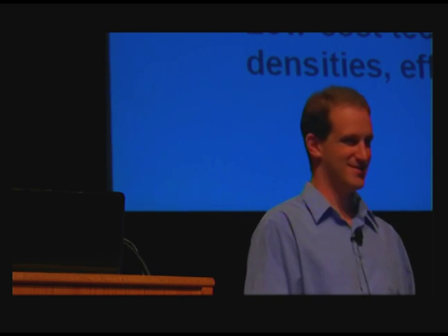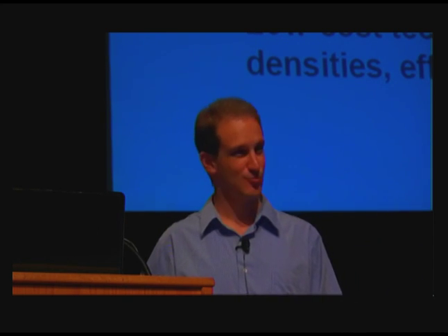Hi. You mentioned you may replace the area which has been used for the decoupling capacitance with the switching capacitance. But is that really equivalent? Because in this case, switching capacitance is basically feeding the DC component, while the decoupling capacitance usually just feeds a very transient current. So I'm just wondering, is that really replaceable?